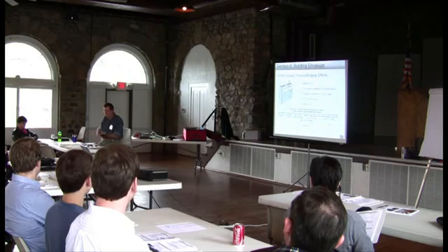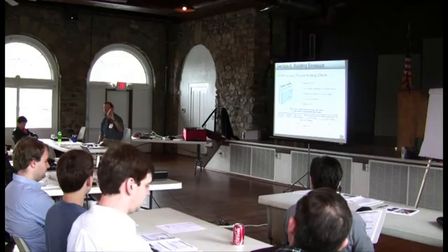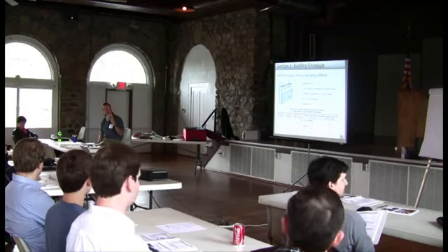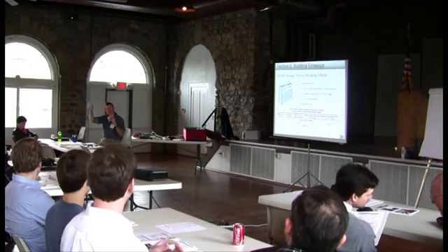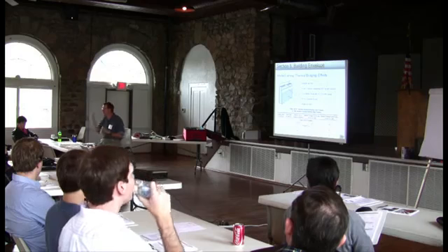And here are a couple of samples. This is a 1-inch version. And they're using a polyiso foam board. So this is a rigid sheathing that also has insulation. It's called SIS, S-I-S, Structural Insulated Sheathing. An inch of this is an R5.5. A half inch of this is an R3. So there are ways of doing this.